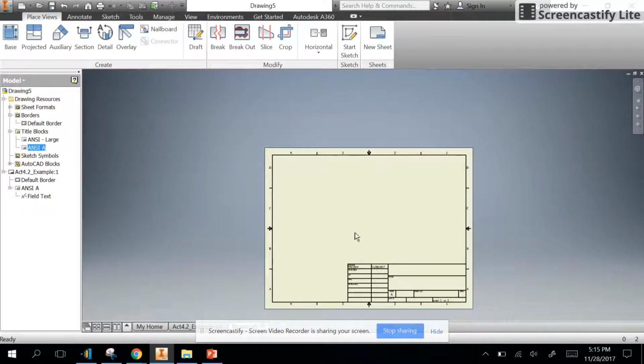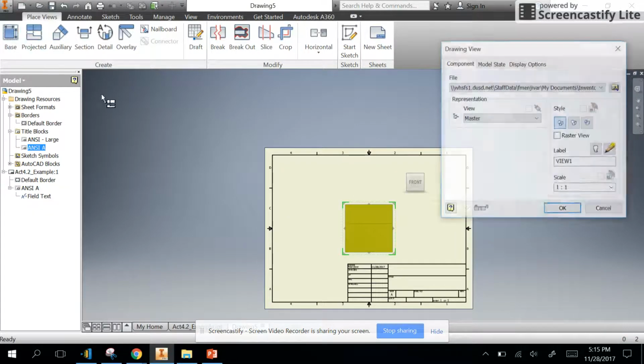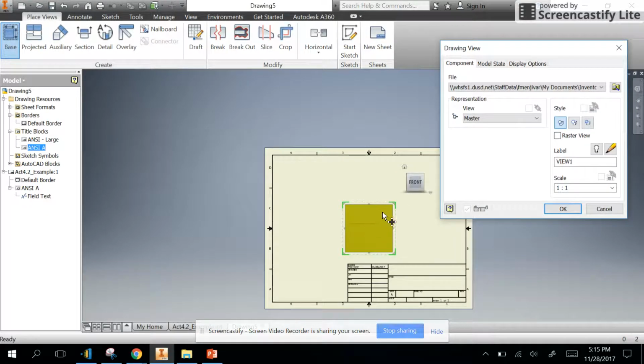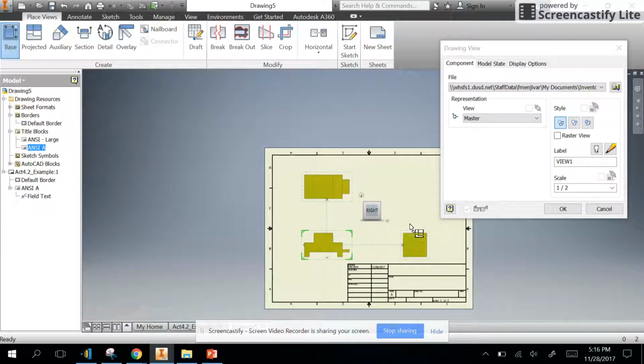All right, now it's time to insert the drawing and create the multi-view. I insert that, and you'll notice, this created an issue for me. The fact that this was now the front is not good. So in order to change what your front view is, you can actually use the view cube and rotate about and select the best front view. So I'm going to go 1, 2, 3, 4. So even though it started as my right side, I selected it and picked it on the bottom left to designate that view as my front.